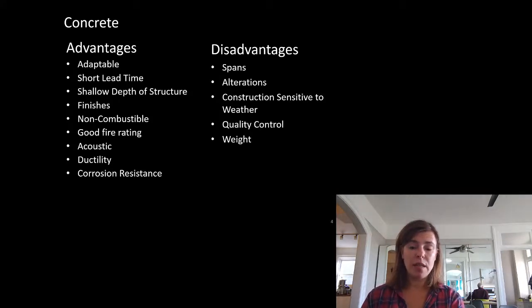Rightly so, I explained this to them and said that I was willing to take a stand on this. I went through and did some quick back of the envelope calculations and just showed that taking the door out was taking out 1% of the lateral system on that floor. I wrote that memo. The building department still didn't want to accept it.